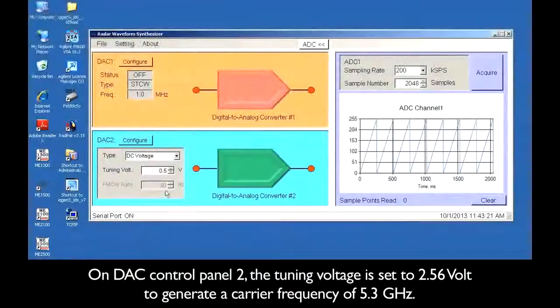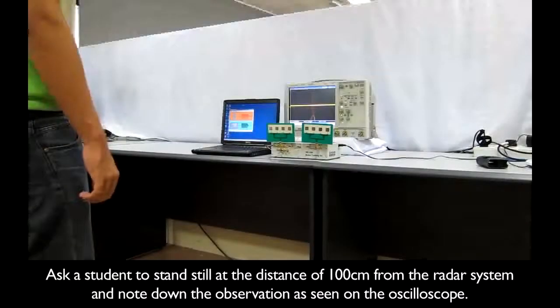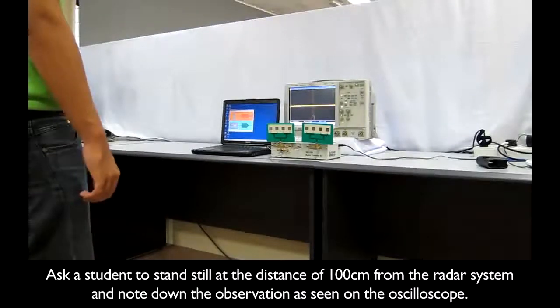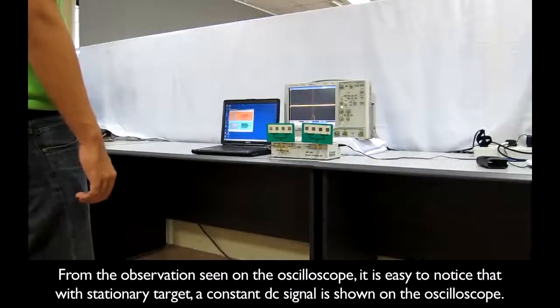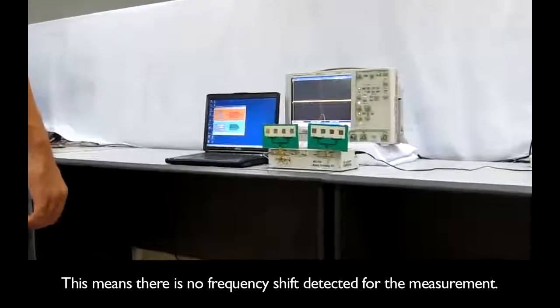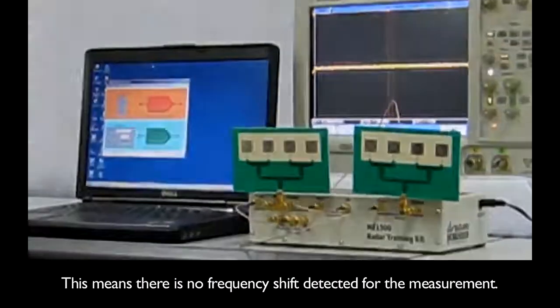On DAC control panel 2, the tuning voltage is set to 2.56 volts to generate a carrier frequency of 5.3 GHz. Ask a student to stand still at a distance of 100 cm from the radar system and note down the observation as seen on the oscilloscope. It is easy to notice that with a stationary target, a constant DC signal is shown on the oscilloscope. This means there is no frequency shift detected for the measurement.